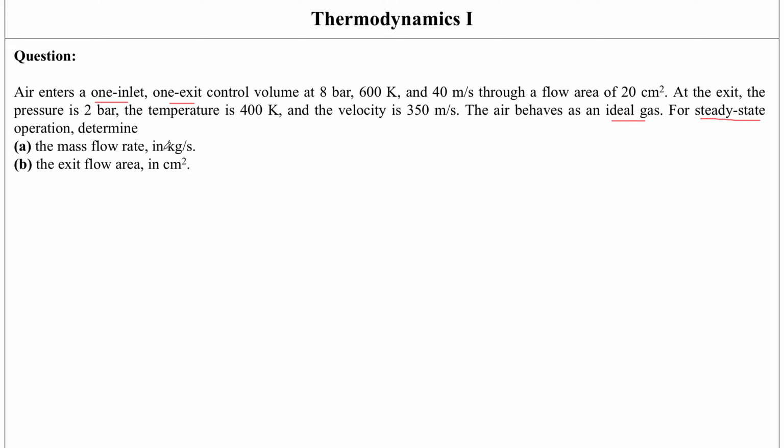So again, we're going to start with applying the conservation of mass principle onto this control volume, and that is going to be the change of mass across the control volume according to time equal to incoming. So if there were multiple inlets, let's say there were 2 inlets, then it would have been M1 plus M2.